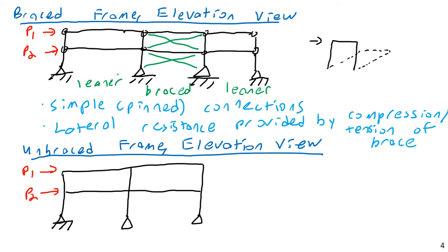Okay, so what if we don't want braces? Well, we can also talk about what the downside of this is. The downside should be fairly obvious. Well, maybe not, especially if you have a building. If you have a simple building where the frame's just along the outside, having braces along the outside, if it was something like a metal building like a workshop or a machine shed, that wouldn't be a problem. But if you have an office building, yes, you can add braces to it, even to exterior bays, but the problem is that this takes up a lot of space. Architects are pretty good at hiding columns. You can usually embed those in walls. But braces, you really can't hide those very well. There are ways to do it, but they're all problematic.